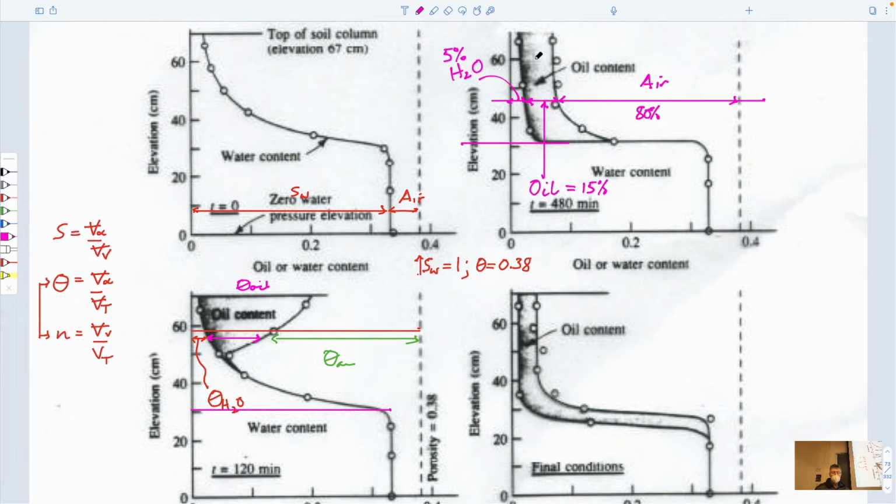This extra supply does two things, I suppose. You can see that this band here is now less. So some of this stuff from here is drained down, and it's become a thinner band in terms of saturation. And obviously the stuff from here has ended up accumulating not on a capillary barrier, but on a pillow. It's buoyed up by the stuff underneath it. So it's trying to compress the fluids in the tension saturated zone by sitting on it, just like sitting on the top of a swimming pool.